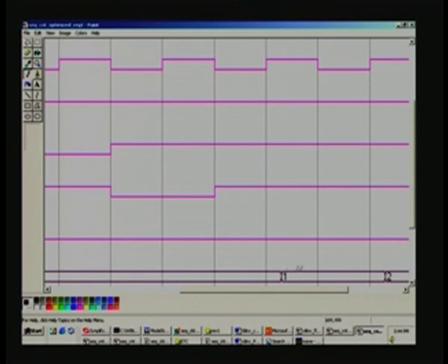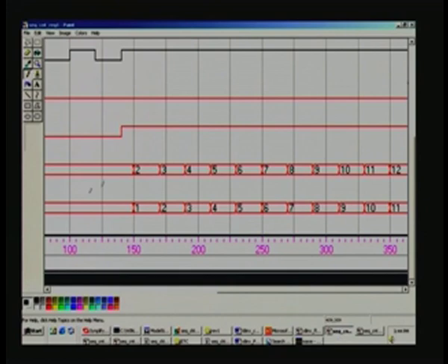That means, after all, the synthesis is aware of the gate delays, because it has mapped onto the actual primitive cells that Xilinx's place and route is ultimately going to use. So whatever place and route details supplied by Xilinx have been incorporated. It may not be in depth, maybe interconnection delays are not fully accounted for, and that is the reason why we need to go for Xilinx place and route. So you have some sort of delay element coming into the picture, that is why you are able to see this. Let us compare this with the previous one.